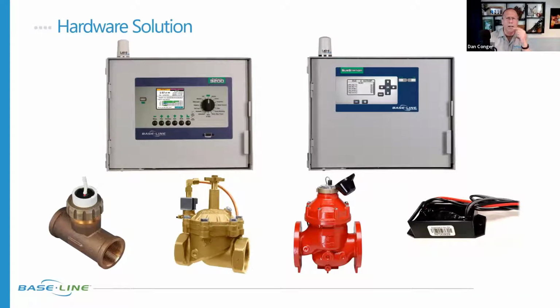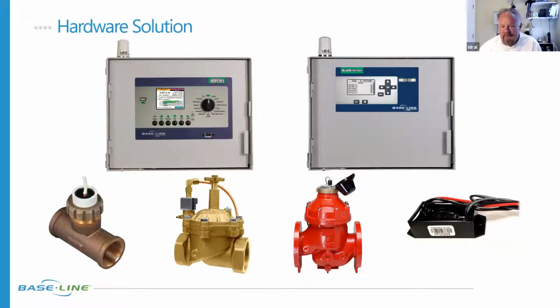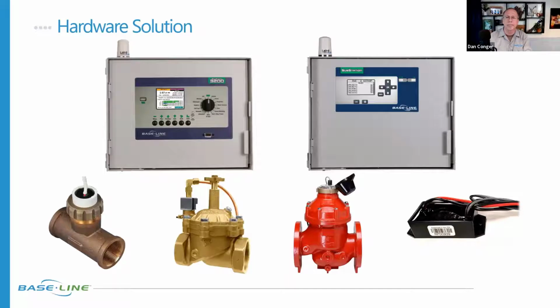So we've got the substation. And so the substation is an extension of the base station 3200. So they could put zones on there. And why did they need the substation, excuse me? Well, they sort of ran a little extra wire and outstripped the specifications electrically of what one controller could do. So we split it in half and basically cut the electrical load in half for both controllers to make sure we keep everybody happy.